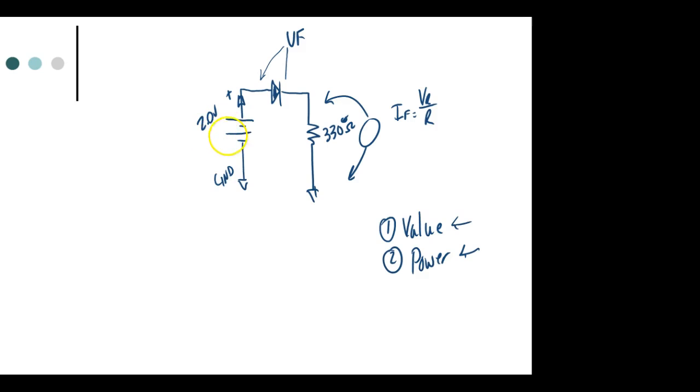Now the problem is that I can't put 0 volts across the diode, because the minimum I can put would be 2 volts. So how would I get 0.1 volts? We're going to start off with 450 millivolts, 500, 550, 600, 650, 700, and 750 millivolts. So I've got this power supply that puts out 2 volts minimum, and I'm trying to get 450 millivolts into my circuit.